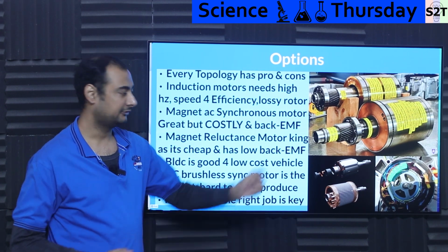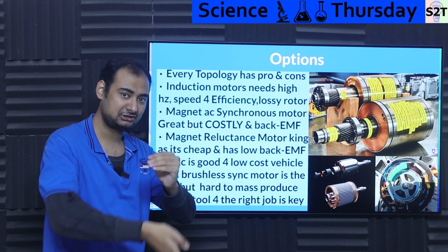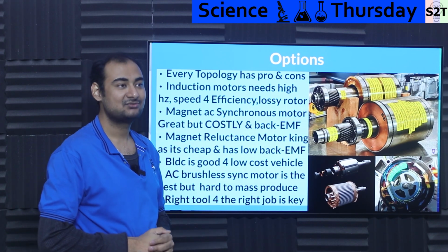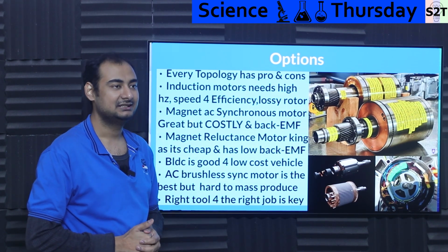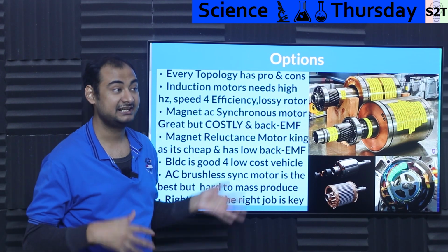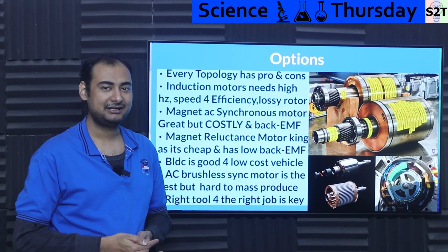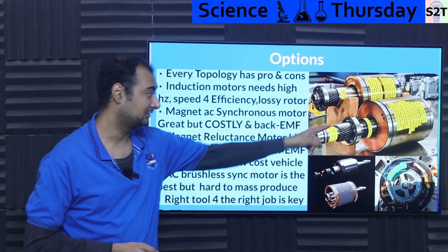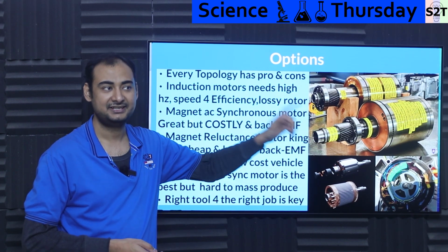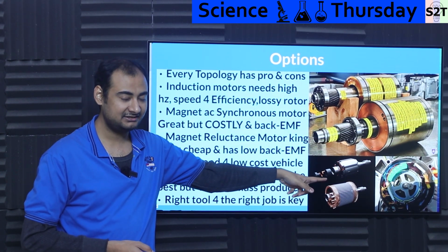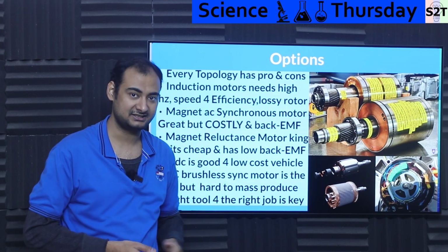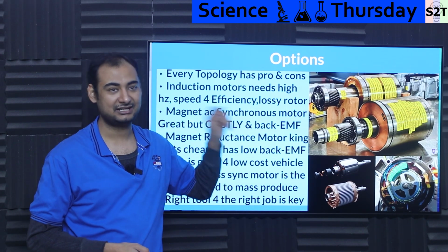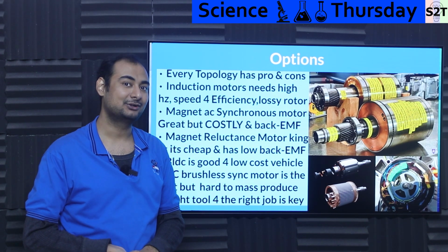Except there is this one thing: the rotor, fundamentally, because there is a slip, has to cut through the magnetic lines rather than being locked to them. The rotor heats up. And this was the brilliant idea of Tesla engineers. They were like, hey, everybody has an induction motor, everybody has a VFD to drive it, so why can we get more power compared to everybody else? What's the limiting factor? It's the runaway heating of the rotor. Let's say the rotor is at 50 degrees Celsius, it has X amount of power. The rotor heats up to 60 degrees Celsius, the power goes down, and it goes down drastically. So they utilized a through hole system to run coolant in the rotor itself. That was the genius idea they had. What if the rotor was cooled?